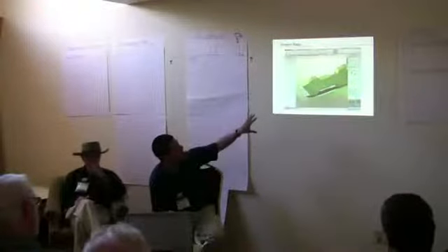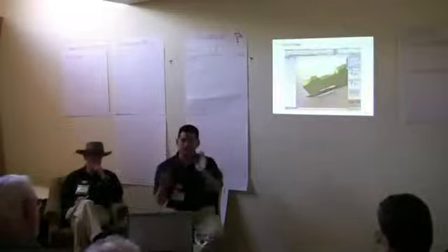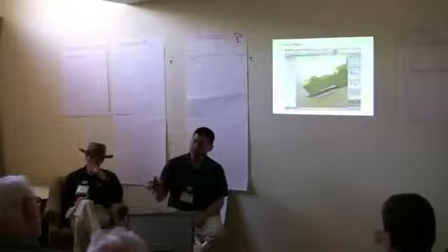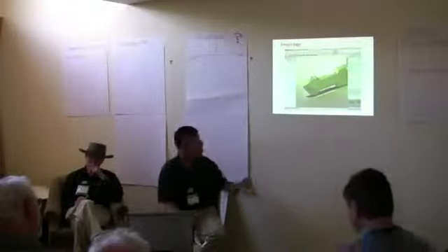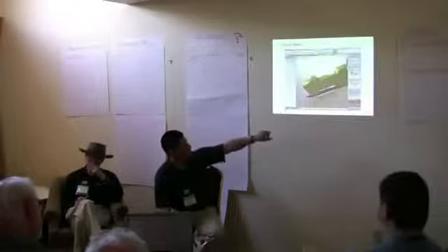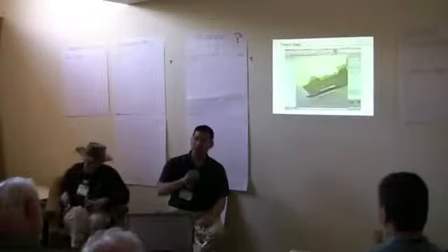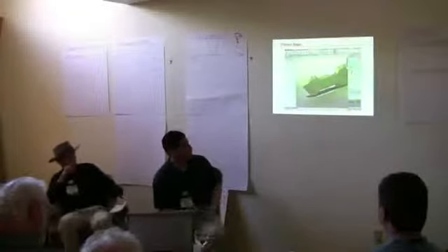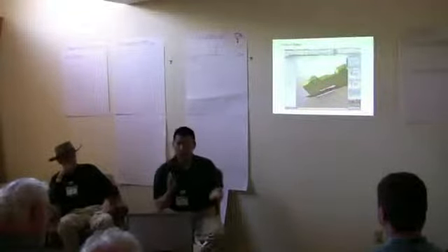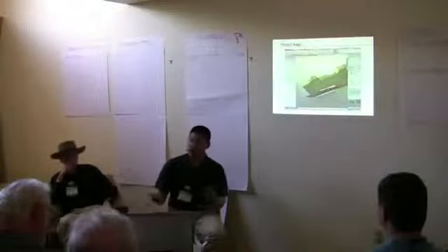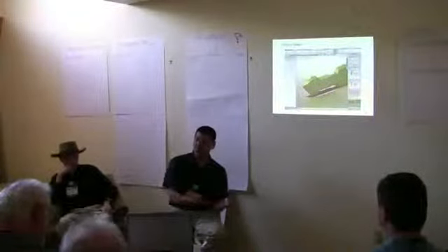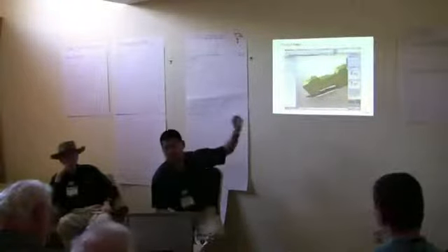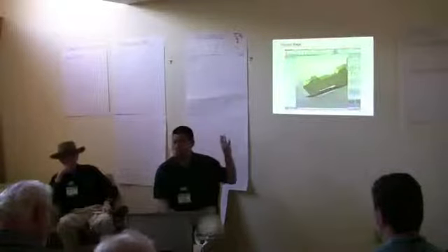And so finally, you get specified just a small number of inputs. Again, we measure the size of the part, and then that information is fed to the PE engine, which helps us in the environmental dashboard down below get that breakdown of the environmental impact in terms of carbon footprint, energy consumed, air acidification, and water eutrophication. And then you can do things like establish a baseline so I can compare how my design is doing relative to a previous iteration on the design. And obviously you can do the assessment on individual parts and on entire assemblies.